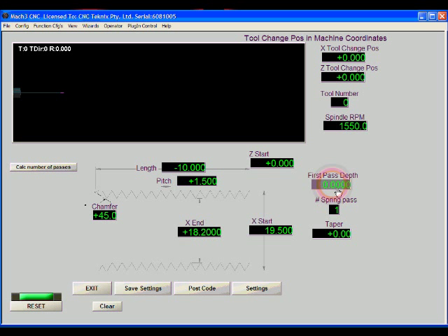The cutting depth of the material, we can do this very much the same, have a 0.3 cut for the main roughing, and we'll finish off with one spring pass, which means it will pass through the material one time at the final cutting depth.